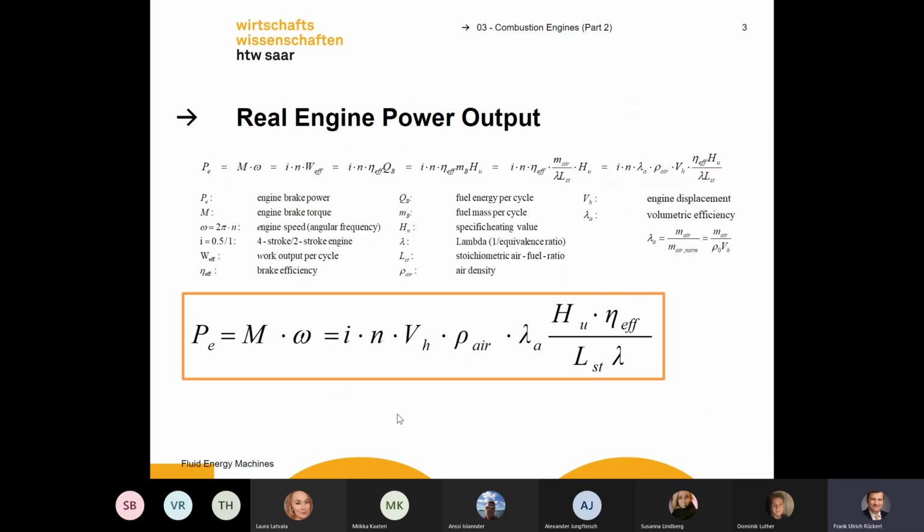How can you calculate the real engine power from a combustion engine? For the power, we use a simple P. You can use the torque and the engine speed, as the angular frequency. You multiply the angular frequency with the torque, and you get the power. Or you can use...